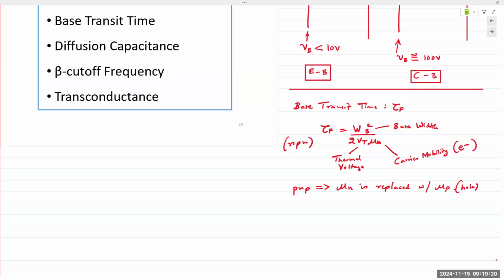Chapters 1 and 2, I would point you there. Essentially, electrons are free to move about. Going back to the basics, holes by themselves are treated as a particle, but a hole is an absence of an electron. So a hole is created when an electron moves out of its spot and goes to another spot, right? And so holes are in response to an electron moving out. And that's one of the reasons why electrons will have a higher mobility than holes.